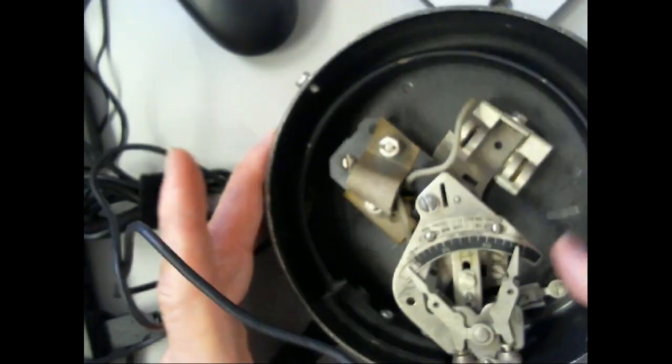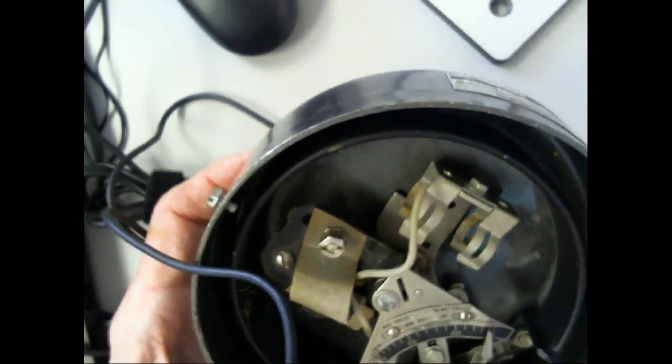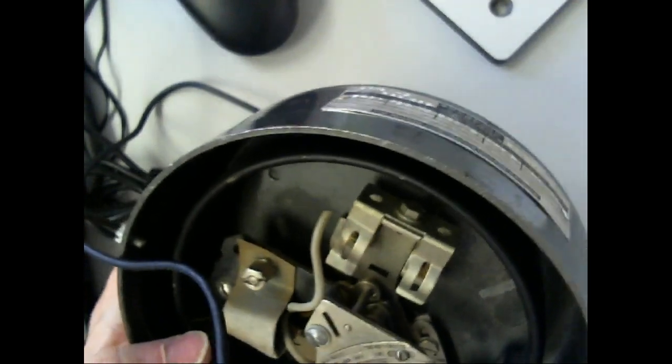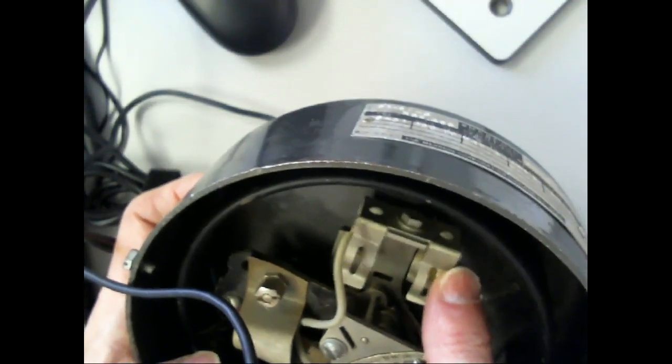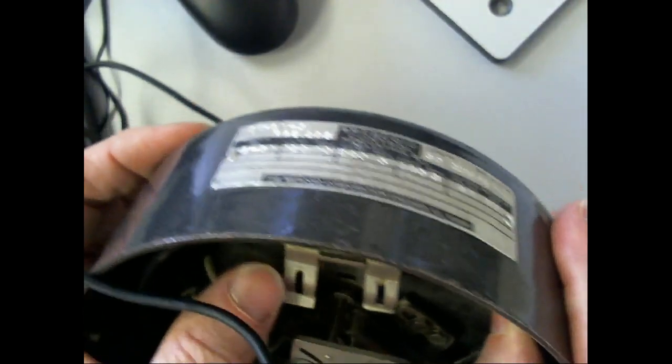So this is hard to see because it doesn't have a good color. But this is the input. This is the Bourdon tube, and then it moves. And then we would have to mount a switch on this, right? You understand, to sense when it got up to a certain pressure. This used what we call a mercury switch. So there was a tube in here full of mercury, and when it got up to a certain level, the thing would swap sides. And when it did, it would close the mercury switch. Now, we don't see many mercury switches anymore. Why?